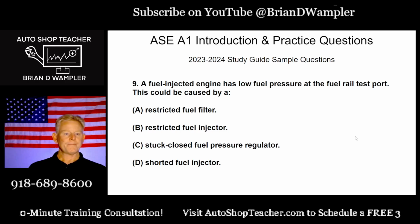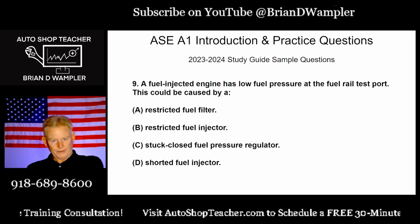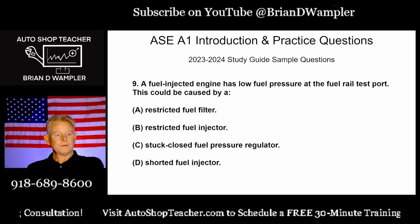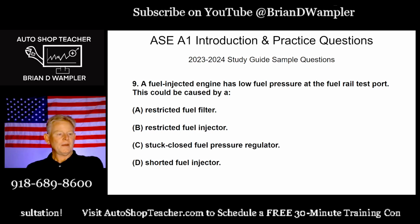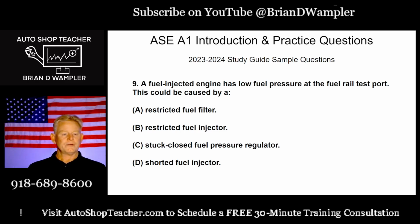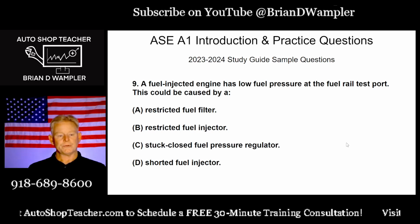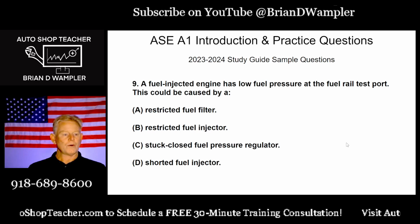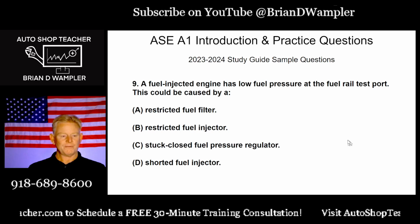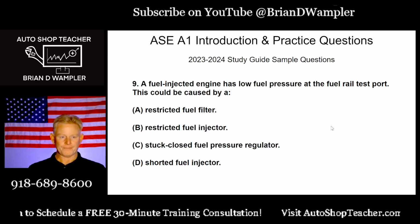Number 9, a fuel-injected engine has low fuel pressure at the fuel rail test port. This could be caused by a restricted fuel filter, a restricted fuel injector, a stuck closed fuel pressure regulator, or a shorted fuel injector. Gotta make sure I read and enunciate properly.